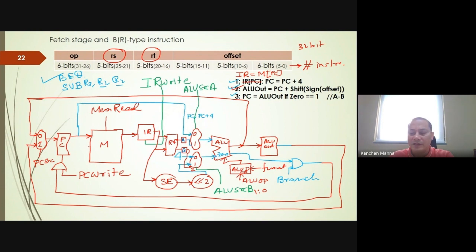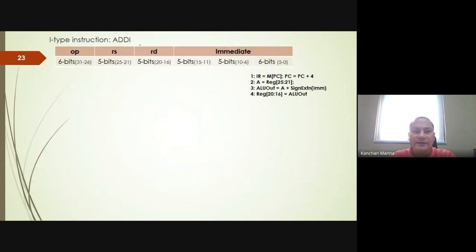Now we'll discuss the other instruction, that is add. So add means, like here we have add, a destination and a source, and then some value, let's say 50. That means we load R1 with the addition of R2 and the offset, that is 50. Okay. Now, we'll perform this operation in 4 steps. So the first step is this one. I think this is common for all instructions.